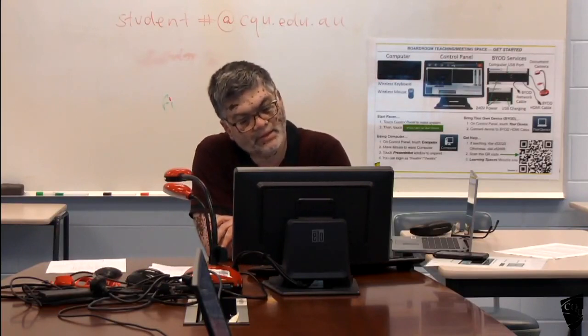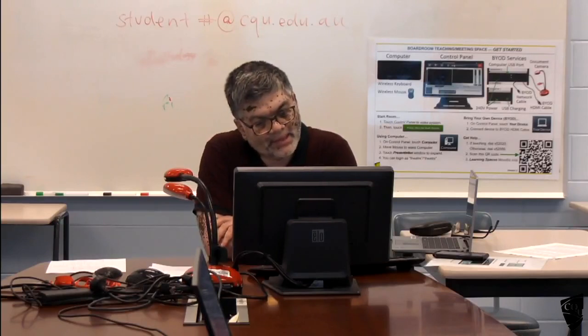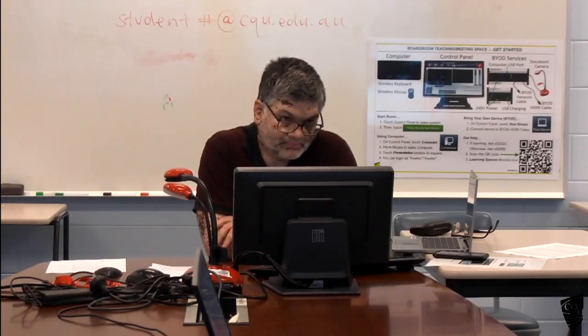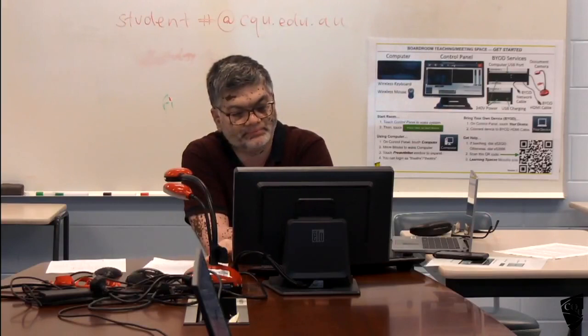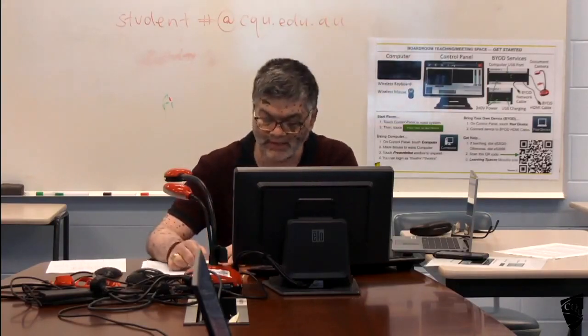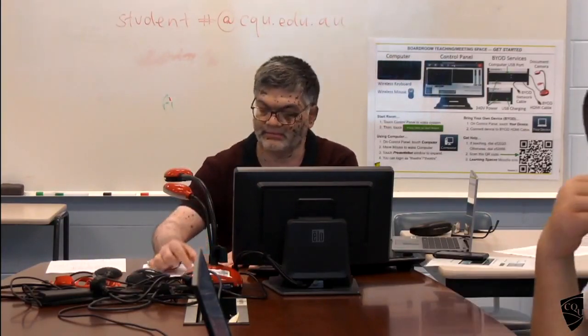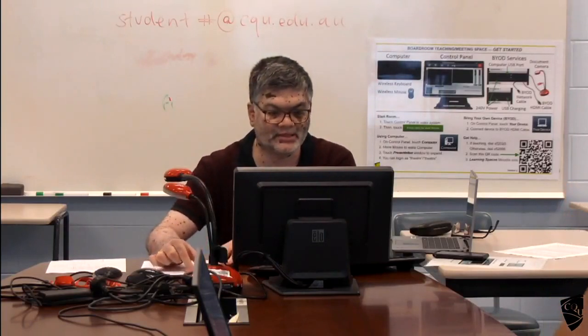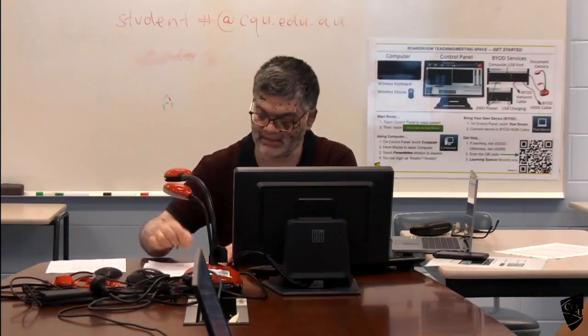Okay, so this is how we develop a bending moment diagram for the design strip. For this entire strip, we have the bending moment diagram. Okay, so at the first support, this much. Okay, this is the end span, this is the end span, this is the end span, something like this. If it is the interior span, something like that.